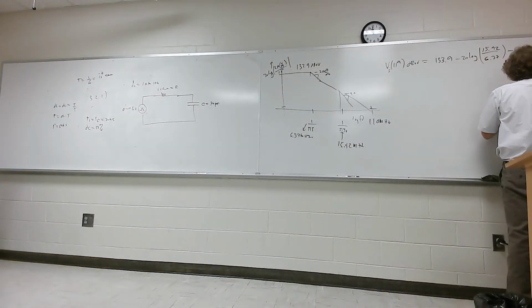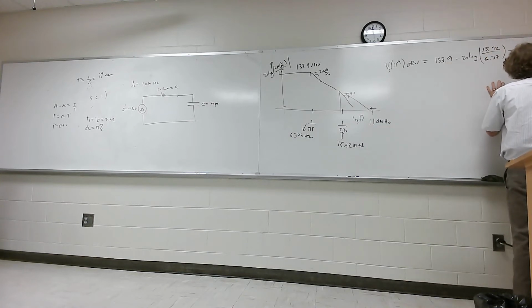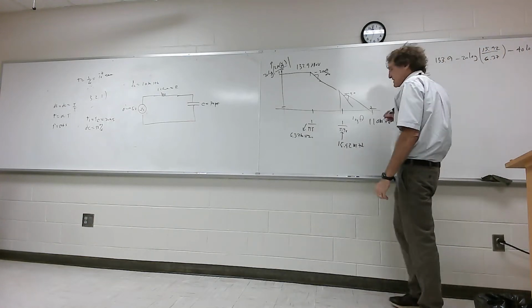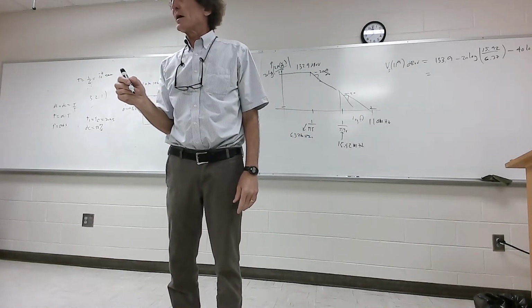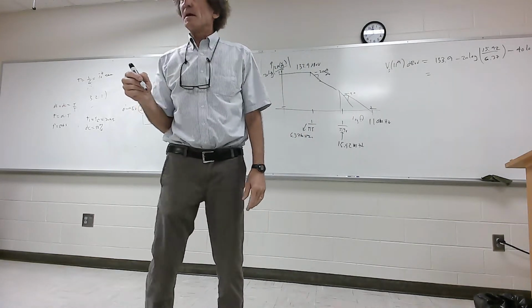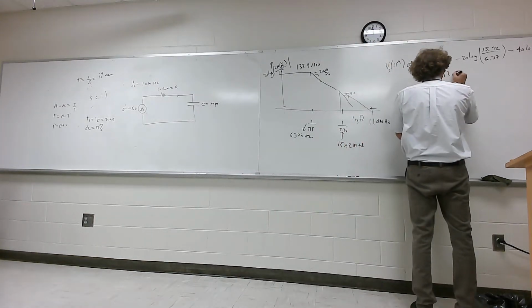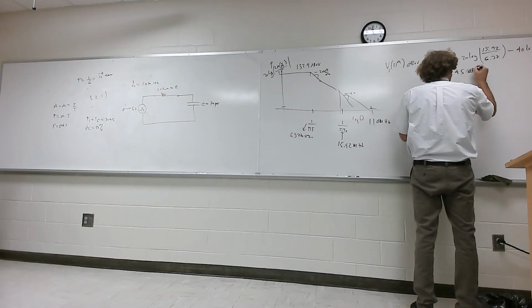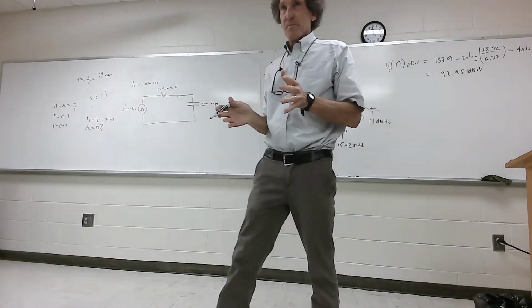So it's 15.92. My upper frequency is this, 110 megahertz. Now I'm just not going to bother to put the meg down. So that has a value, and I think it was 92, but you check me on that. Anybody confirm or deny? Is it 92 exactly? 92.45? So this is 92.45 dB microvolts, right? That's the source value.